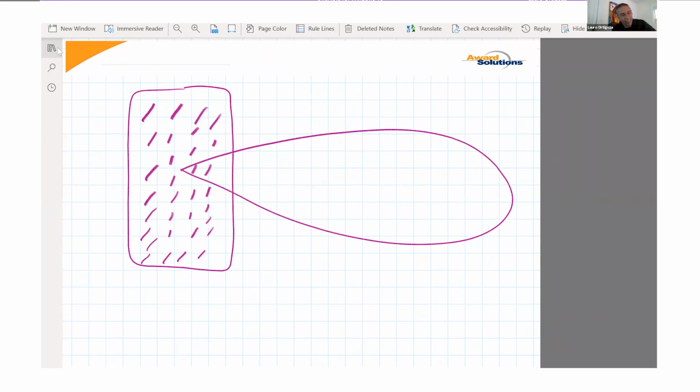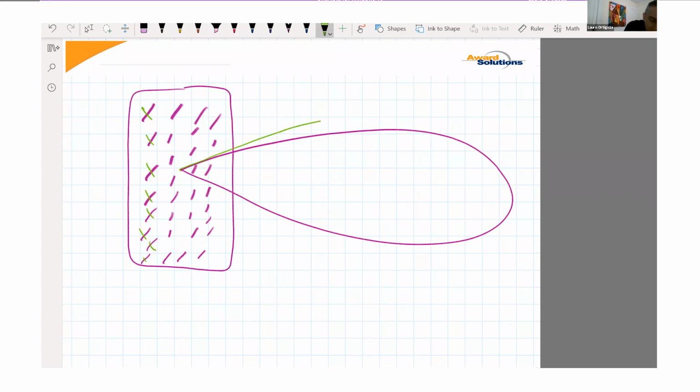So the difference between 4T4R and MIMO 4x4 is that in MIMO 4x4, you have to have 4 ports, 4 subarrays or 4 antennas, and each antenna transmits a given layer. So you have the 4 layers in MIMO 4x4. They're different information. It is as if one of your kids was playing football, and then you have you, your wife, your mom, and your dad, and all of you send a given message to your kid who's playing football, right?